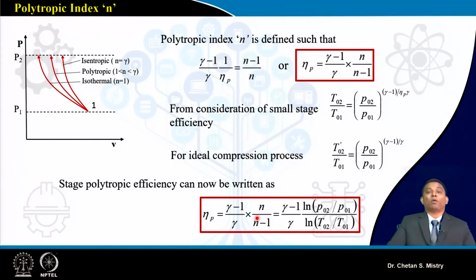Then we discussed adiabatic efficiency and what we mean by polytropic efficiency. Later we realized that polytropic efficiency has gained its own importance, giving the idea that increasing the number of stages of the compressor gives higher overall adiabatic efficiency. But adding stages in an axial flow compressor is a burden, and people avoid that kind of situation.